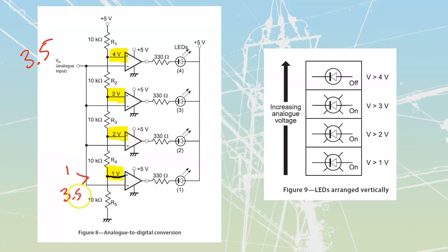I'm going to see that 3.5 is a positive 2.5 more. It is plus 2.5 when I do this comparison of those two values. If it is a positive value of voltage coming into an inverting input, that means the positive is going to get driven out to become a negative, right? Positives change to negatives through this inverting, which means that this thing is going to switch hard towards the ground. Note that there's no feedback.